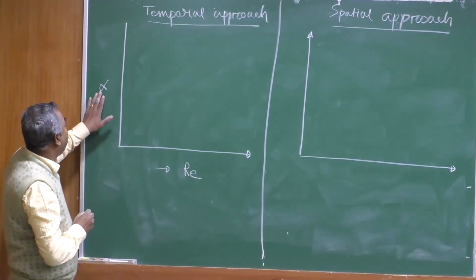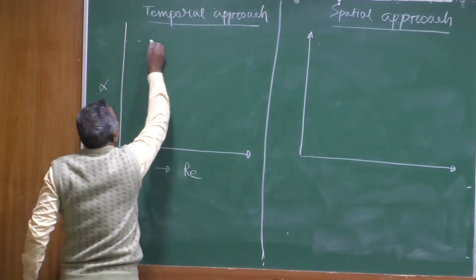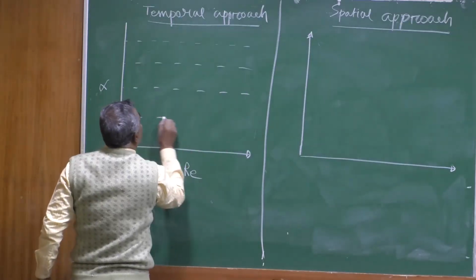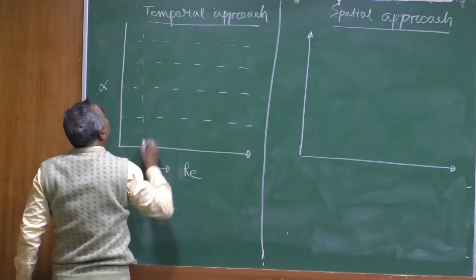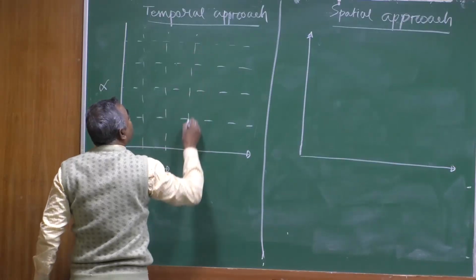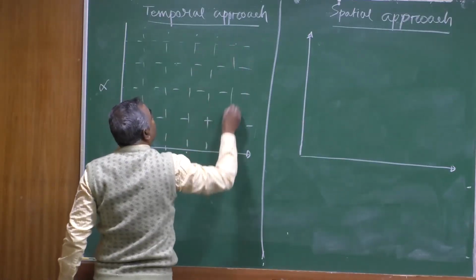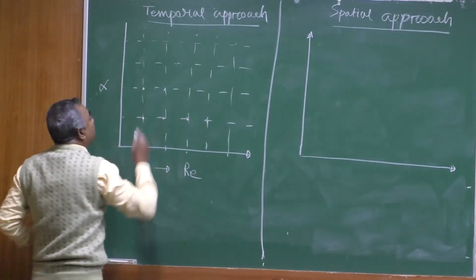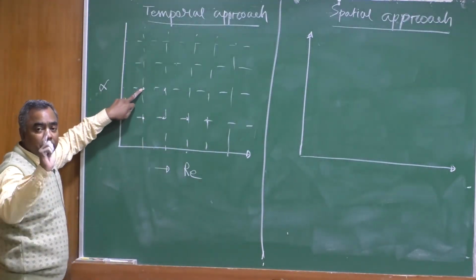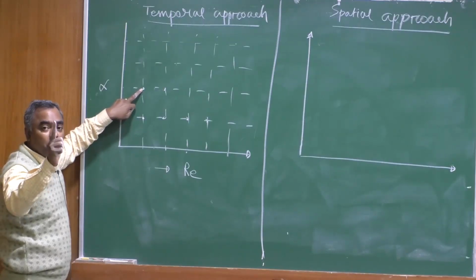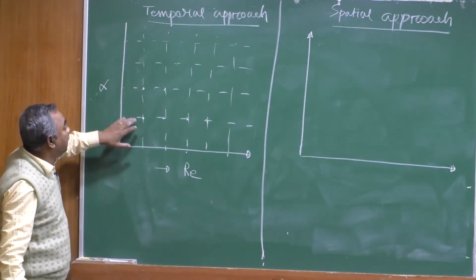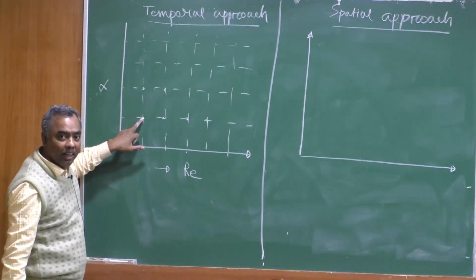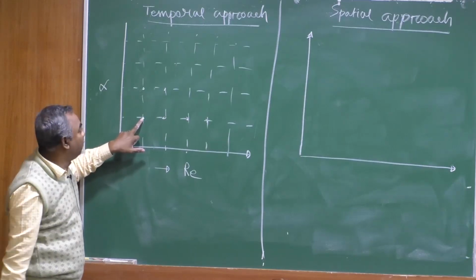Okay. So, we have a mesh, let us say an invisible mesh. Using this invisible mesh, we have solved the equation at different points, meaning we have considered a fine enough mesh, and for each and every value of this mesh point we have solved the equation. That means, for each and every point we have one maximum Ci value, which is the most unstable Ci we are considering. That means, at each and every point in this plane you have a value of Ci which is the most unstable value.